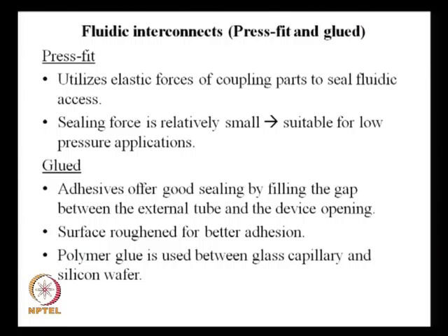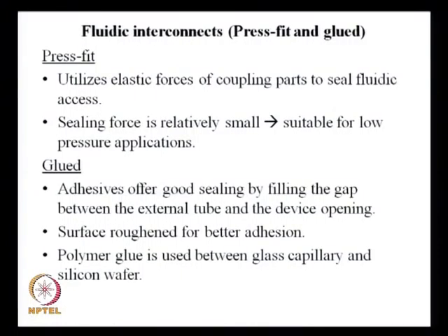So, that problem is there. So, this press fit arrangements, these are very popular as long as you are working with a low pressure system, because this is more of a just take this and press this in, put little bit of pressure, little bit of force, and the interconnect will go in and seal. However, it can seal only up to certain pressure. The other method is what you call glued.